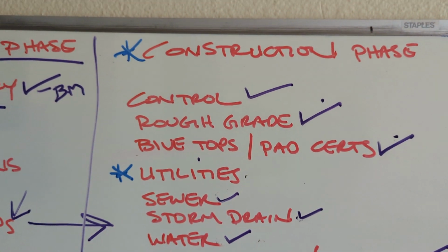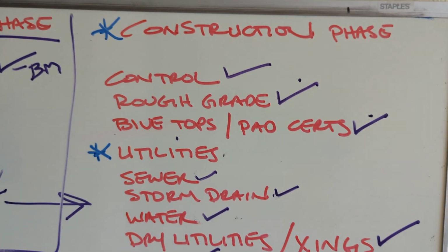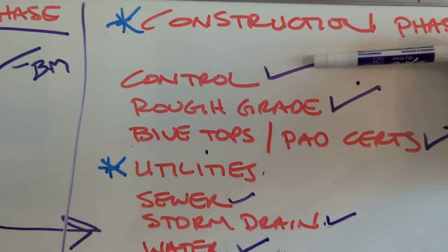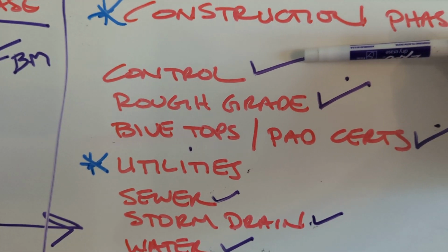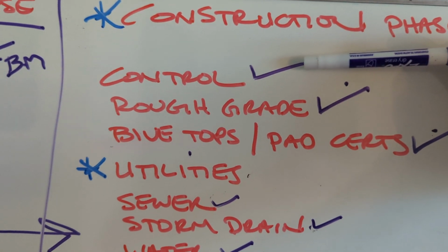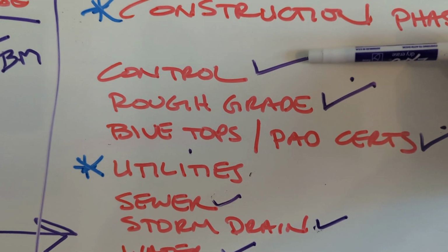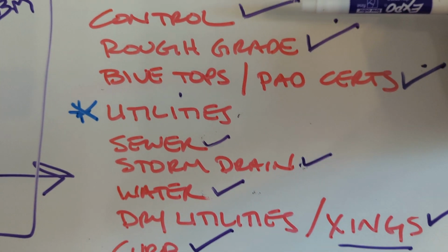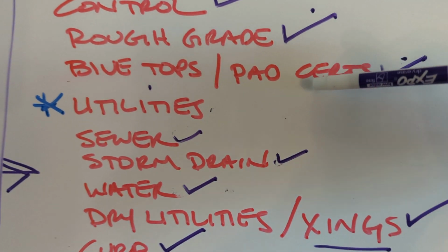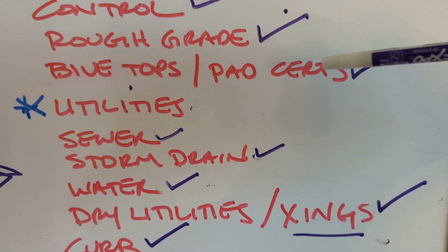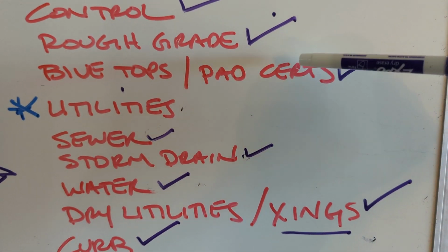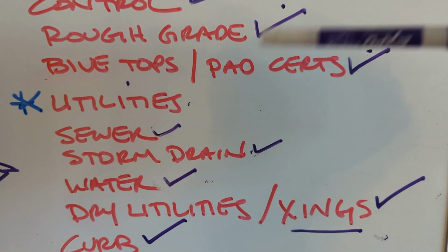And then start just building good habits, set good control points, things that aren't going to move. Set them below grade if you can, so if somebody scrapes it or something, you don't lose it. Know the reason why we do a lot of this stuff, especially certifications. A lot of times, job sites can't move to the next step until they get their certification letter for inspectors and all that stuff.